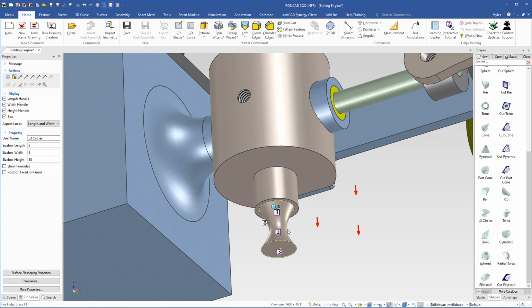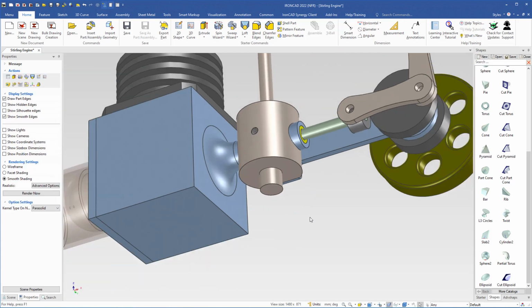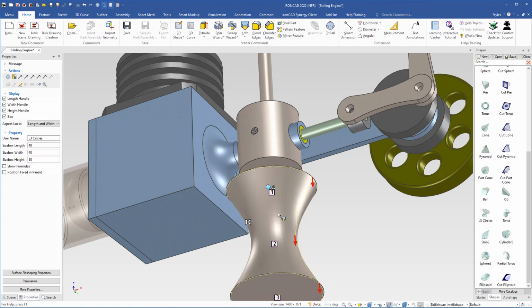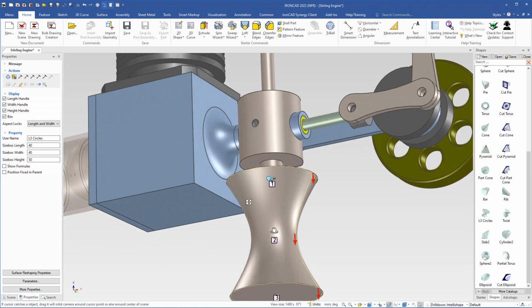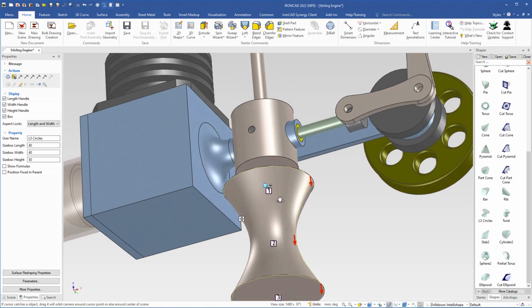And the size of this lofted feature depends on the distance between the camera and the pillar. If the camera would have been further away, this lofted feature would have been in the right size. So for instance, I will delete this one and I will show you how it works. I will zoom out a bit and then I will drag a lofted feature, drop it here, and it will have a different size, and now it has the right size, and it will have this length of 50 millimeters.